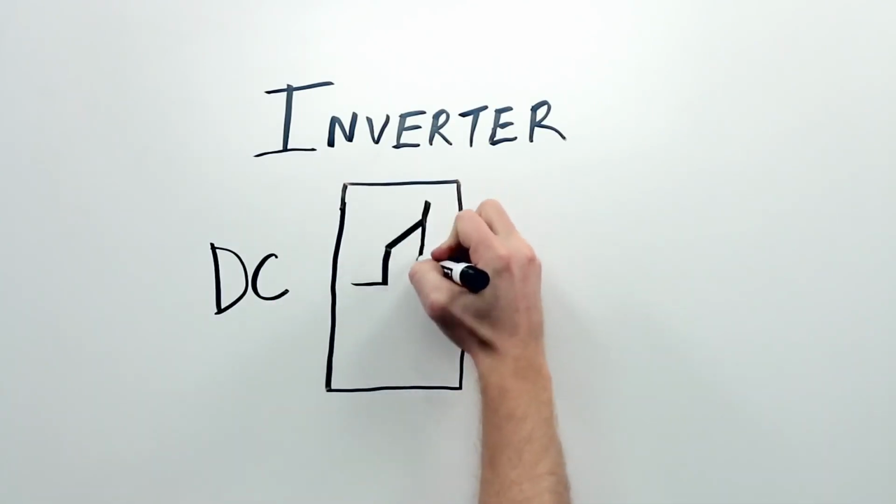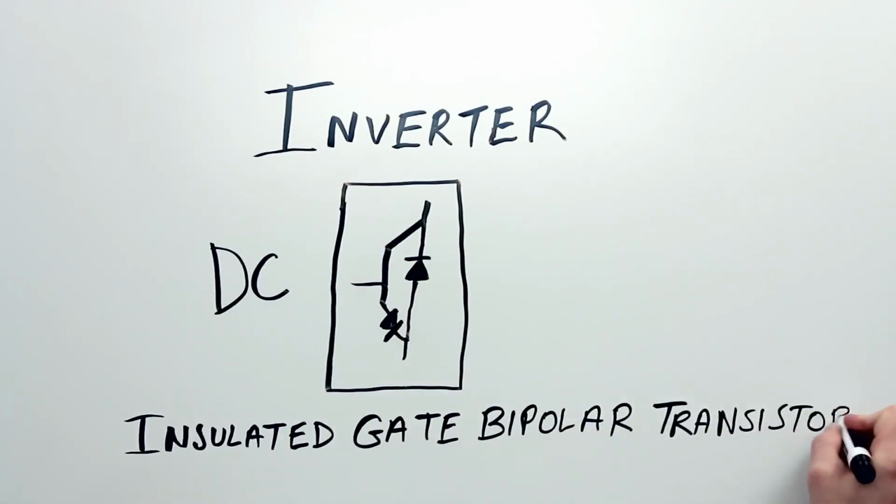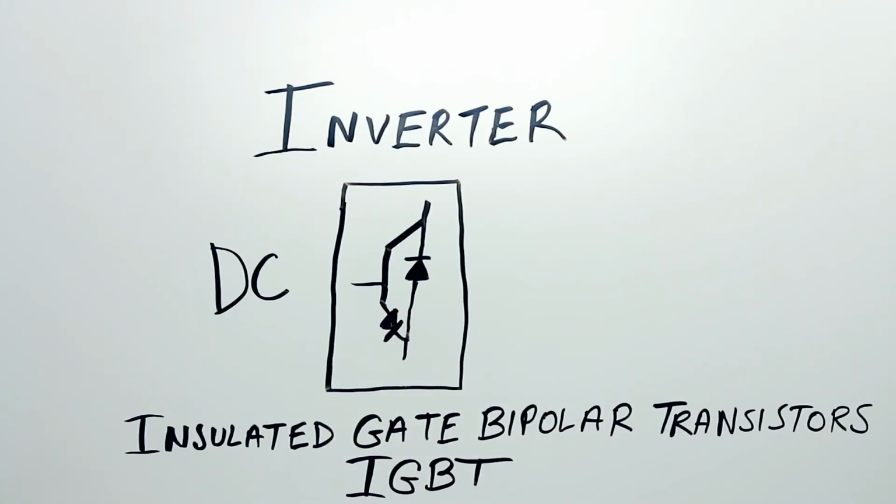Inside the inverter, there are small circuit board components called insulated gate bipolar transistors, which, as you can imagine, everyone calls IGBTs. The IGBTs act as little triggers that take the DC power and fire it out in short bursts. So, the IGBTs spit out the DC in a short burst, then another, then another. Then they let out the DC a little longer, and then a little longer, and then a little longer, and then a little shorter. Then they take the DC and flip the polarity.